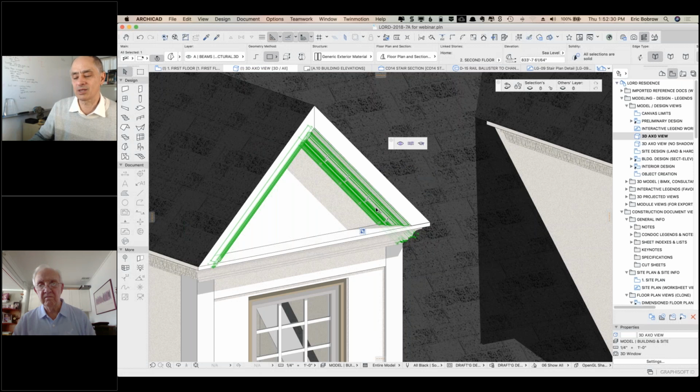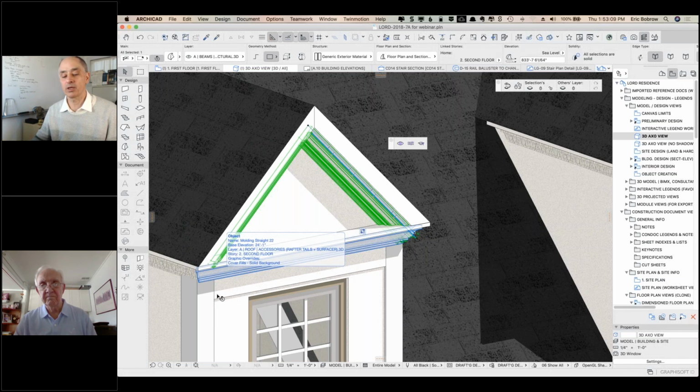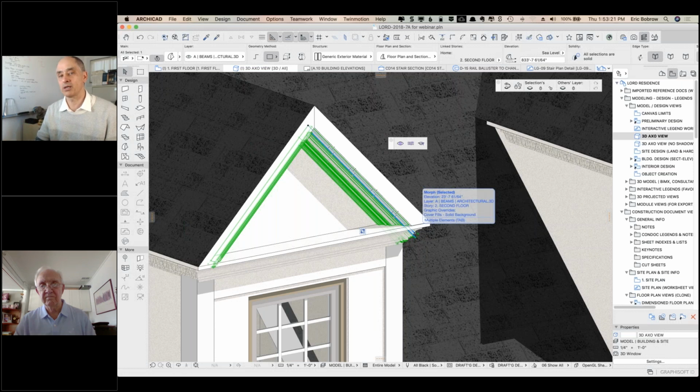The Morph Tool I won't demonstrate today, but this was one of those things where, when Lou brought the question to me, I said, let me see. We tried two or three different ways to do it, and the Morph Tool seemed ultimately the simplest. With the Morph Tool, you can take existing forms and rotate them or do other things. One possibility is to create these moldings on the ground, convert them into a morph, and just flip them up. Another possibility is to take the profile shape and extrude it, creating an axis line, and then turn a corner and use the tube option in the morph to have a nice clean corner as it goes around.